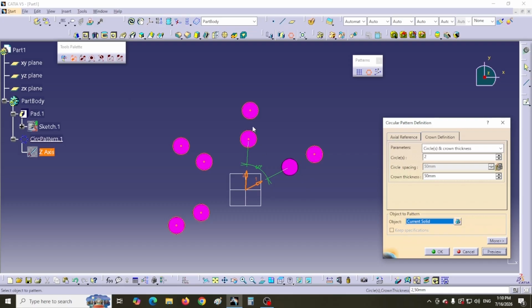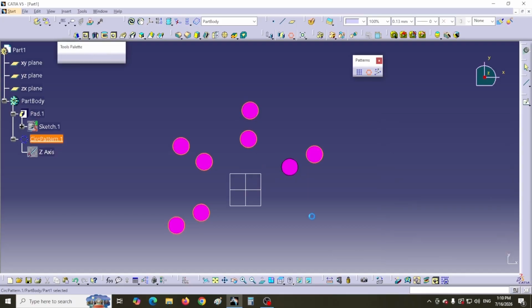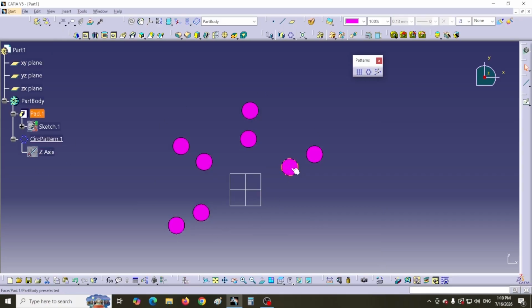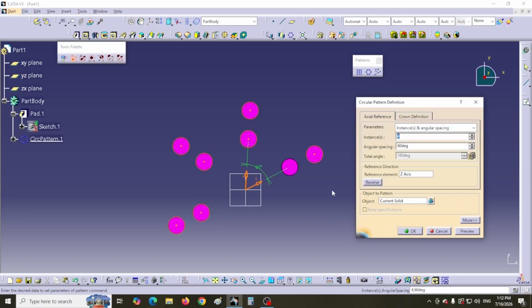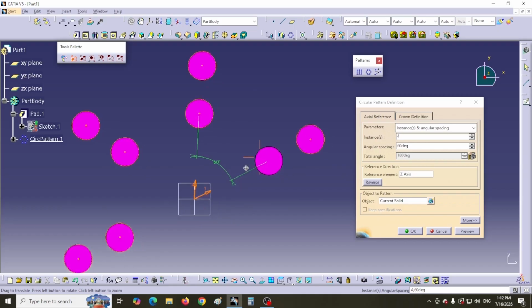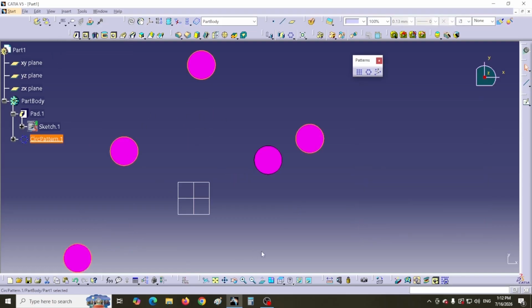If we want to delete one of the cylinders, we cannot do this from the created shapes. The reason is that all these shapes are a single pattern. We must first open the pattern setting window from the design tree. Then click on the anchor point of the desired element. By clicking on OK, you can see that the element is deleted.